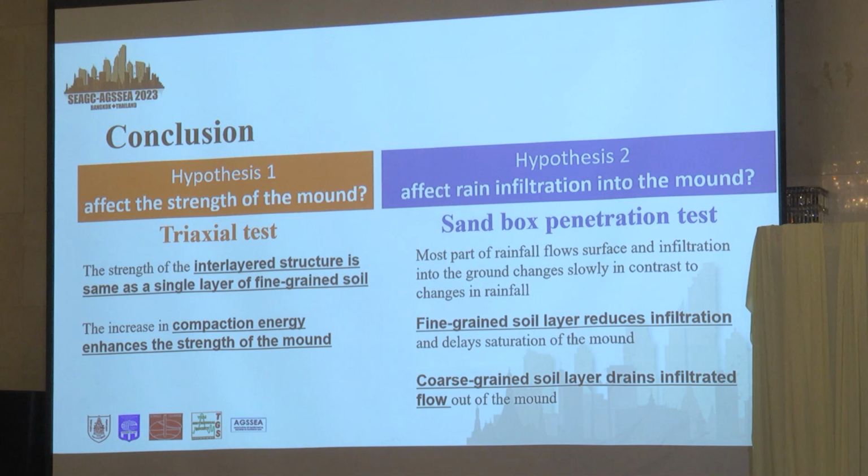Here is the conclusion. In this study, a triaxial compression test and a sandbox infiltration test were conducted with two hypotheses regarding the role of the interlayered structure of fine and coarse-grained soil. The result is that in the triaxial test, the strength of the interlayered structure is the same as a single layer of fine-grained soil, and increasing the compaction energy enhances the strength of the mound.